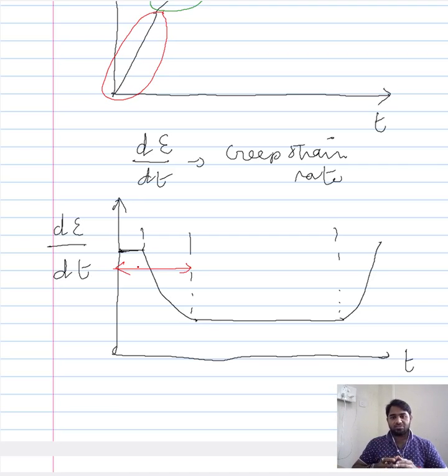And here, as you can see, region 1 comprises 2 sections: the instantaneous creep region, wherein the slope or the creep rate is constant, which is followed by the transient creep region, characterized by the decrease in the creep rate. So this would be our stage 1, which is expressed in terms of the slope of the creep, or the creep strain rate.